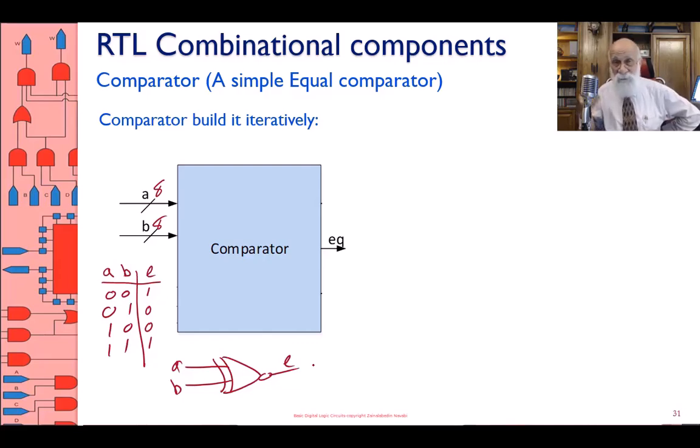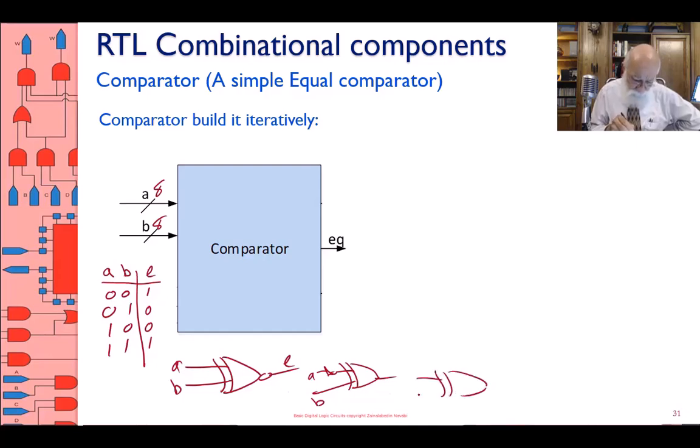Okay, that's why it's XNOR. It turns out the good thing about XNOR is that if you complement A or complement B, not that I'm going to use this, but I'm just giving you some XNOR information. These three circuits are exactly equal. So if you complement A or you complement B or you complement the output, the circuits are the same.